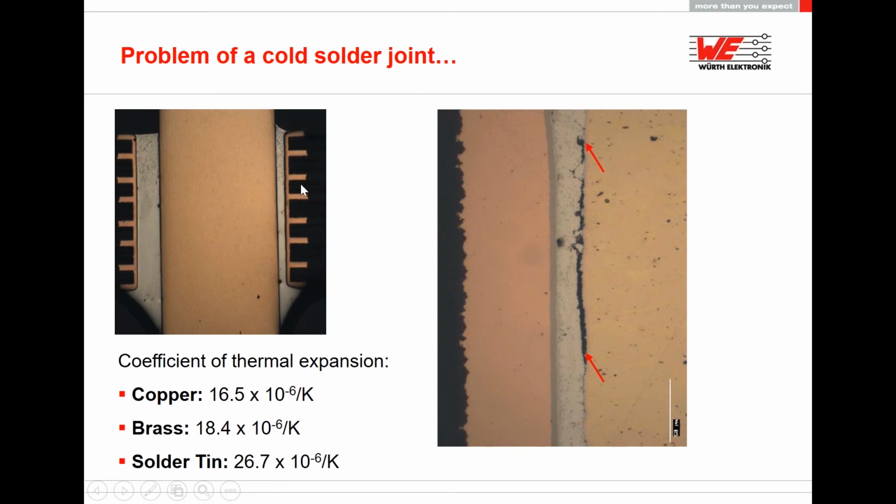And you also need to bring all the current down into the other layers. It's not that easy because you are not really connecting directly into all layers. You need more small vias around the solder part. And then you, of course, also have the solder with higher resistance. So with the SMT components, you are quite limited. Especially for high currents, you need big cross sections, and with bigger cross sections, you have much higher expansion.